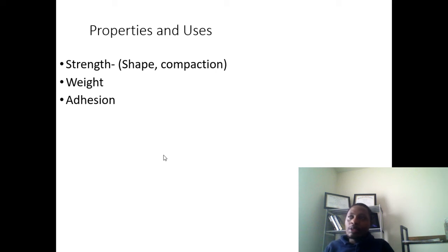For example, if you are doing a building, okay, and you are doing, say, a flat roof, and you're doing concrete, okay, so you have something so heavy on your roof, it's going to affect the structural integrity of your building, say the foundation. Okay, especially if it was not designed to carry that kind of weight. Okay, so that property is also so much important.